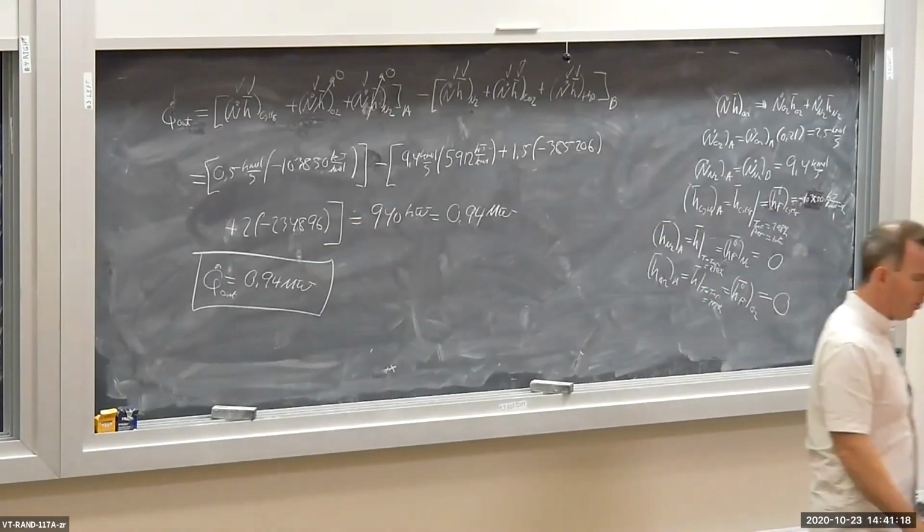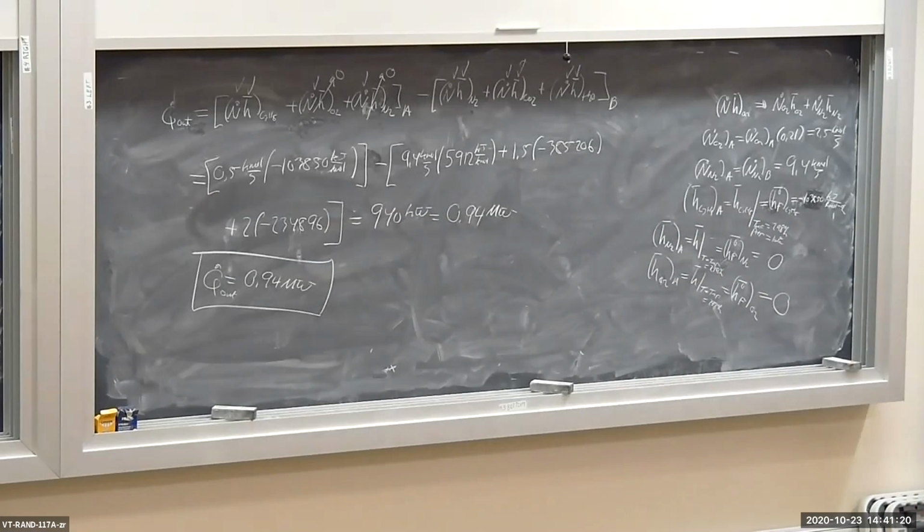Okay, there you go. Very simple, not really much going on there that's different than mixtures, except we have to be careful in evaluating the absolute enthalpy of the reactants and the products. If we don't include the chemistry in the enthalpy calculation, we're not going to get the right heat transfer. Notice all these are huge numbers.